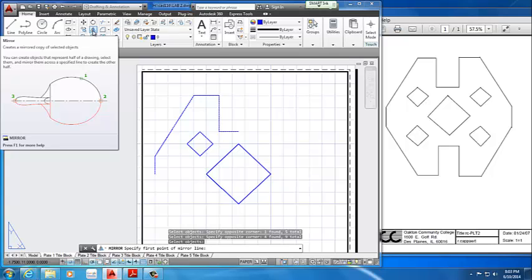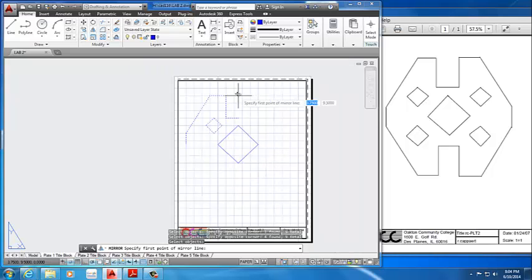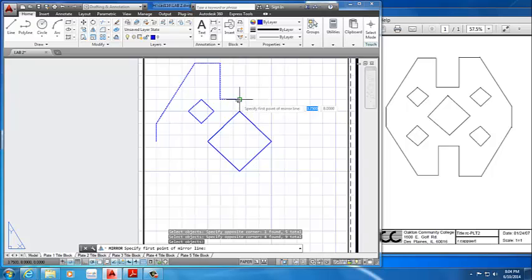So what we're going to do is create a line that's going to be centered. You can either guess that that's going to be the center, use the endpoint here of the line and go down, because that's going to be how you're going to mirror it over, or you can even use the diamond shape as a reference. So you select it from the top or at any of this center line area, you move your mouse down and you'll see a somewhat of a demo of what it's going to be. If you have your mouse off to the side, it's not going to work. But if you have it perfectly 90 degrees, you'll see that it works perfectly.